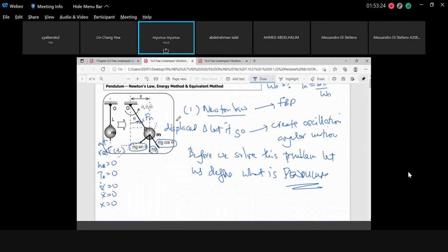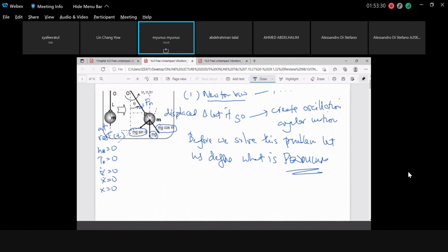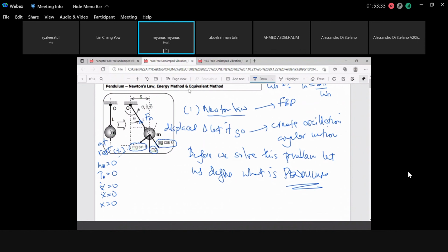So you can use three different methods. One will be Newton's law, which is not very difficult. We try to use Newton's law, the simplest one. You have summation of M about O equal to I theta double dot. What you learn in dynamics is I O alpha, but in principle you learn from the general equation, summation of M equal to I alpha plus m a d.